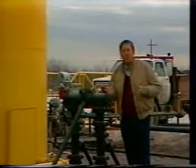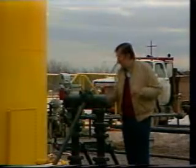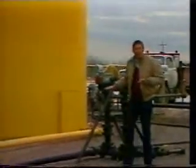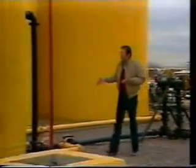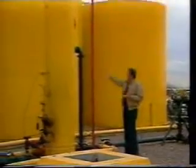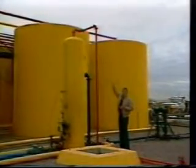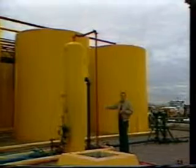All of the production then from the wells that are going to produce into this tank battery come into it through this header right here. In this black line then we have oil, gas, and water. And that oil, gas, and water, first stop is to this three-phase separator. The oil, gas, and water come in through the black line about the center of the separator, and off of that, the top comes the gas, the bottom the water, and at the mid-phase, the oil.